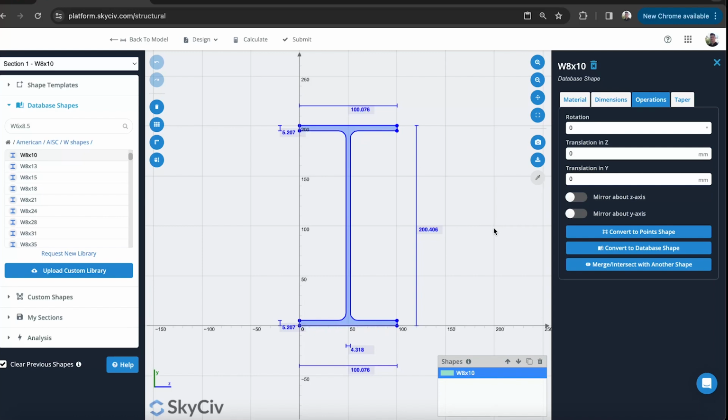Whereas if you load it in this direction, so in the Z direction, or the weak axis, you're creating a bending moment about Y, and the section doesn't have too much material on the outside, or these outer ends, the top and bottom ends, and it's just not designed to take as much moment force on that weak axis. So there's a lot less capacity in this cross section to take a load in that direction. So it's really important to consider and understand those concepts. We've got a major or strong axis here and a weak axis here, and we want to make sure that our beam is orientated in a way that it's taking the most force in this direction.